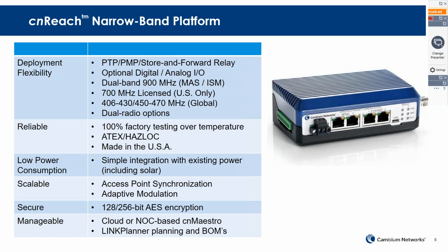You can use any Modbus TCP master to poll the radio to get the things' readings, and you can even send control messages, still Modbus TCP control messages.